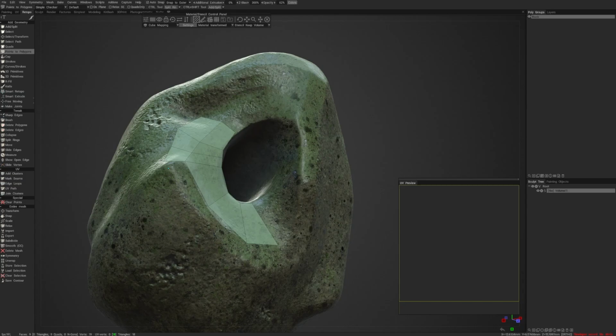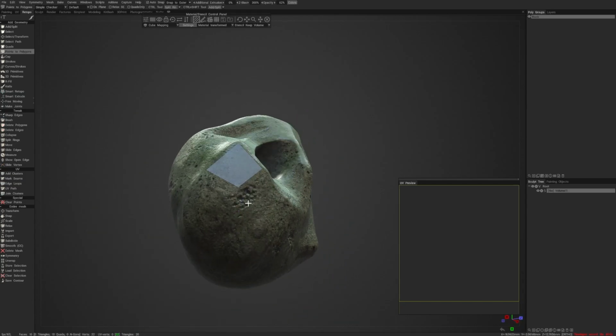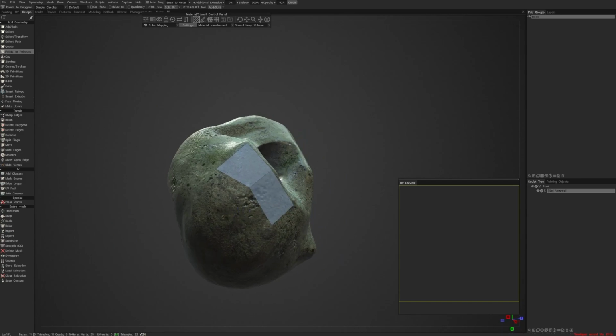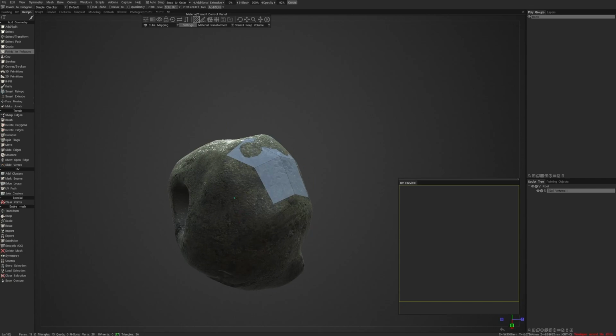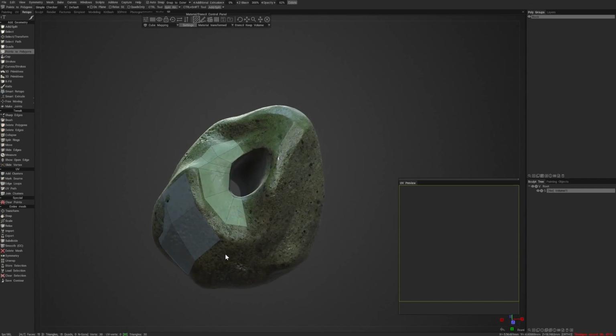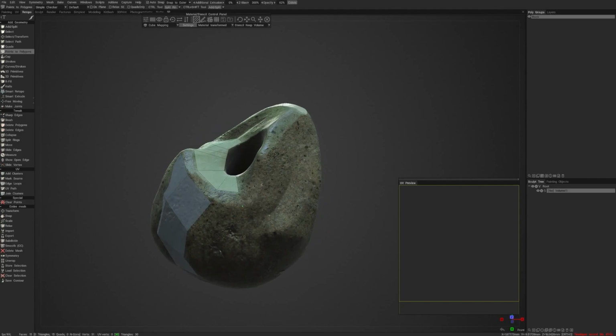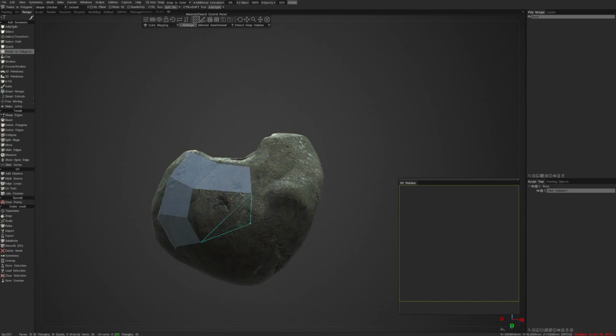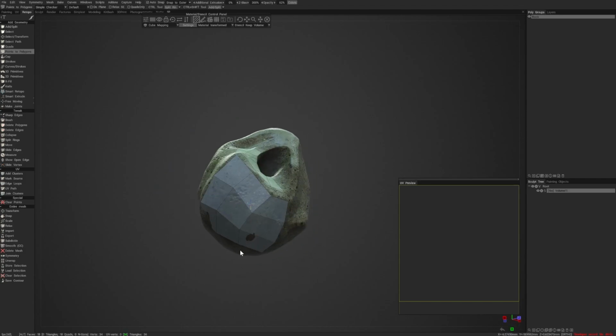And what I have learned to save myself time is I make as big polygons as I can using points faces, and then I can go in after the fact and chop it up, make it smaller. But I want to do as much of the heavy lifting as I can this way.